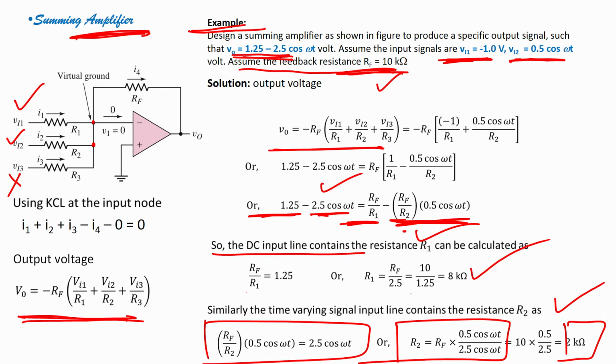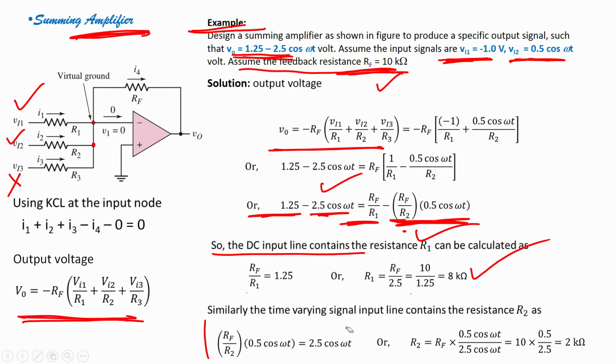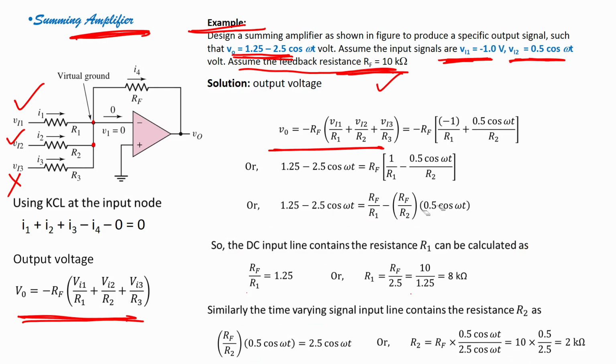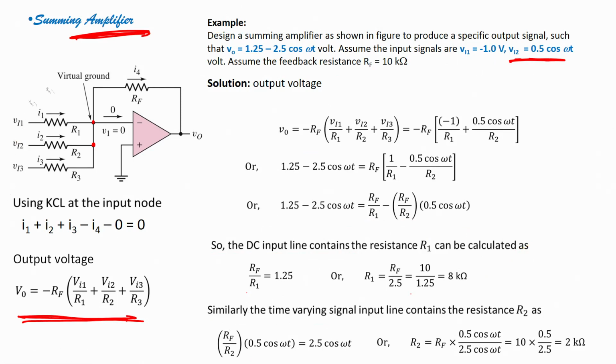Alright, so it is very easy. Let us quickly once again see what we have done with the summing amplifier. A summing amplifier is nothing but an inverting amplifier connected in a way that you have more than one input voltage, so that you can take a summation of those input voltages. It can be n numbers, okay, like this it can go until n.